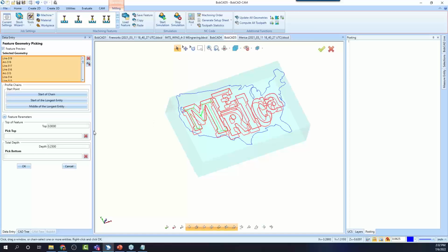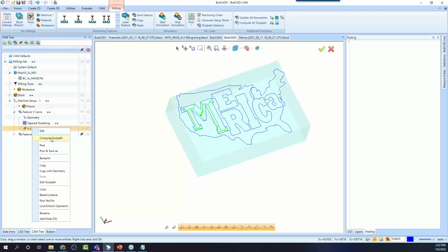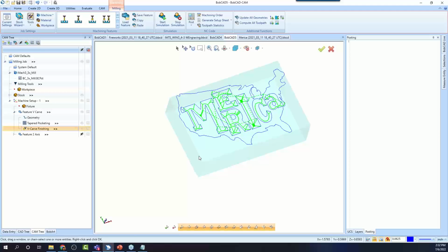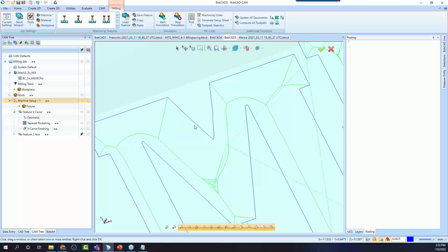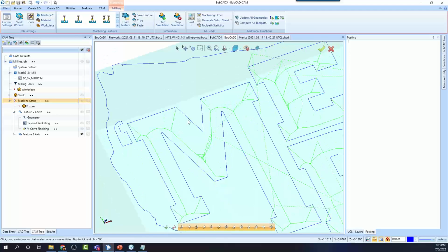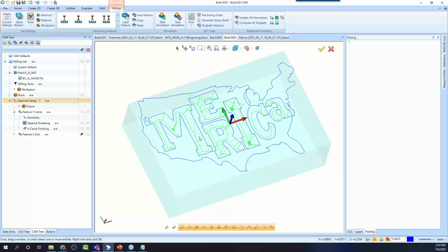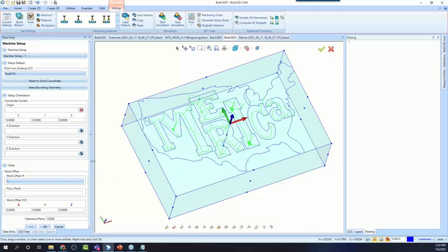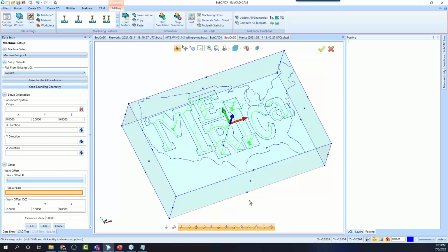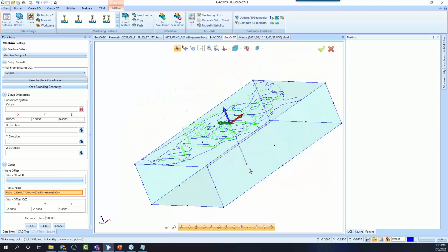This is just an example of V Carve lettering, where we're using the tool to cut that into the letter. Unlike a pocket routine, where the tool rounds over and the depth would be the same, using V Carve the tool will climb up the corners and give you a sharp chiseled look, and you can do some really cool things. So in this case, I did the letters there. Let me go ahead and get this into position where it will simulate on the machine.